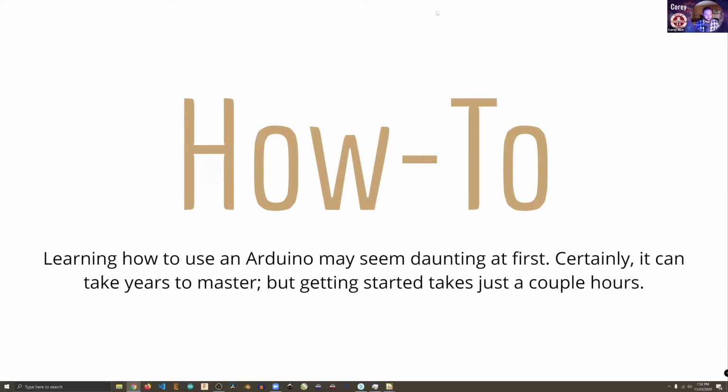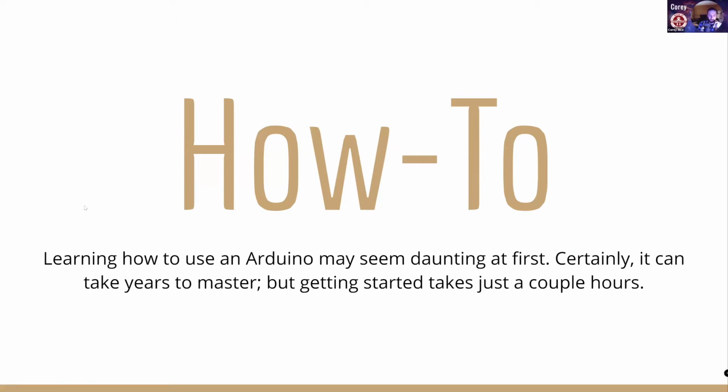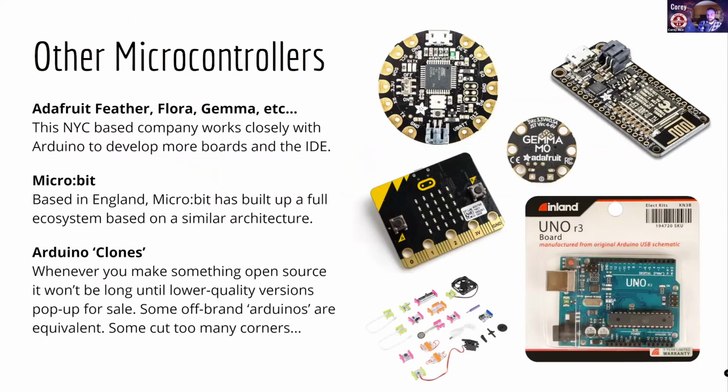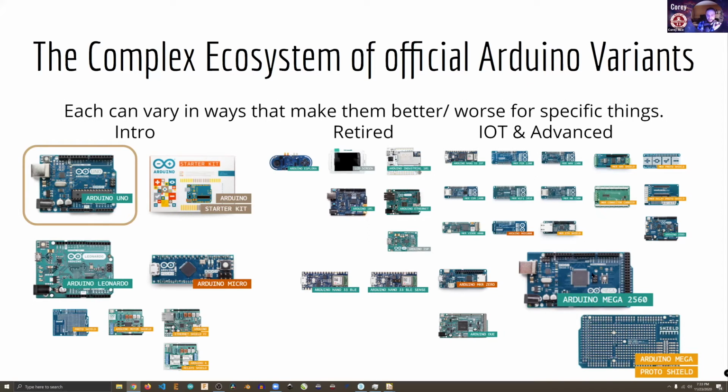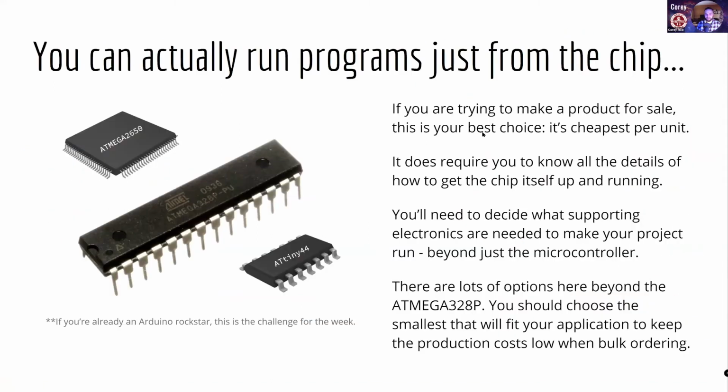The ATmega, oh, that's a good question. Is the ATmega less buggy than the Arduino board? Is it more predictable? I would say that it's neither, that they're both equally buggy. You might have fewer problems with the Mega because it's got more memory. You're less likely to hit some of the ceilings in projects that you might hit with an Uno. And this week, while we go into the how-to, I'm going to try and give you some strategies that will make it less likely you'll hit buggy things. There are definitely some tricks to doing Arduino well so that it isn't buggy, but it's going to feel buggy to start. So let's hop over to the how-to part.